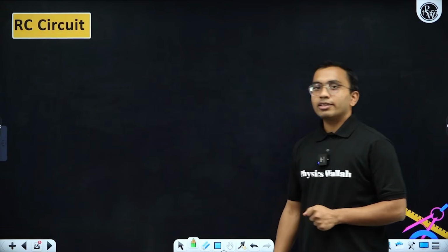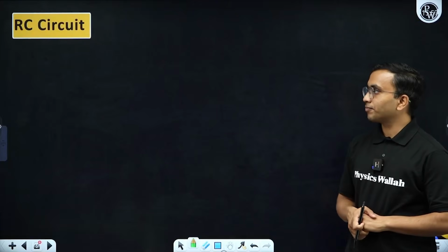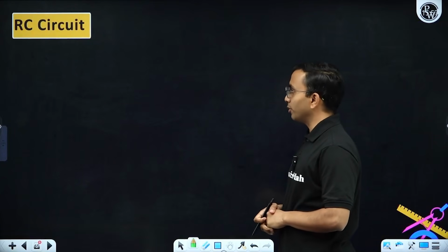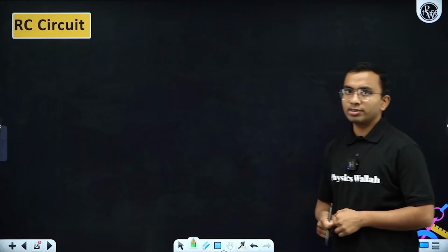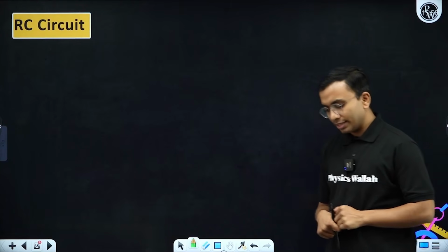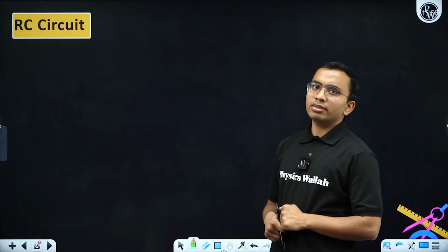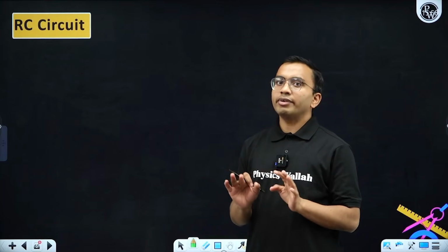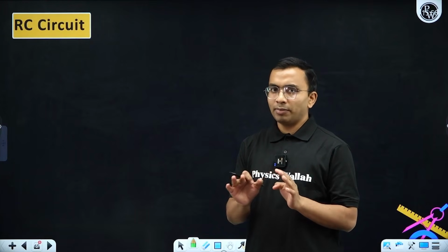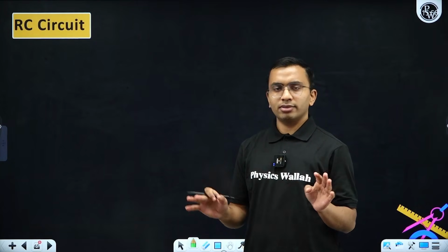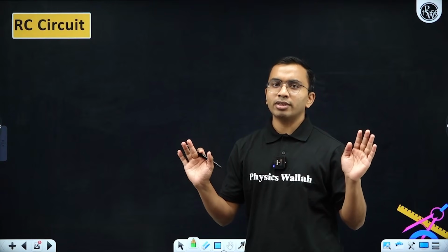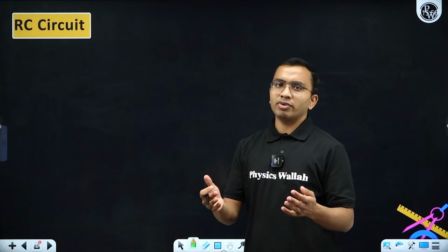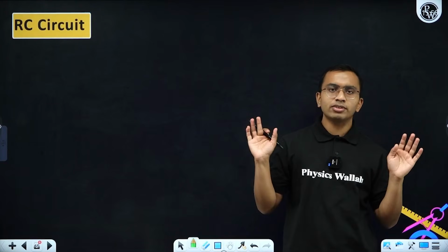Okay, now we are coming to RC circuit. This is also one of the important portions, but in advanced, RC circuit is more asked. In mains, RC circuit is asked, but not at that difficult level. You just need to understand how to analyze the steady states. Like at steady state, we know the capacitor will behave like an open circuit. At t equals 0, the capacitor will behave like a short circuit. These things you need to understand.